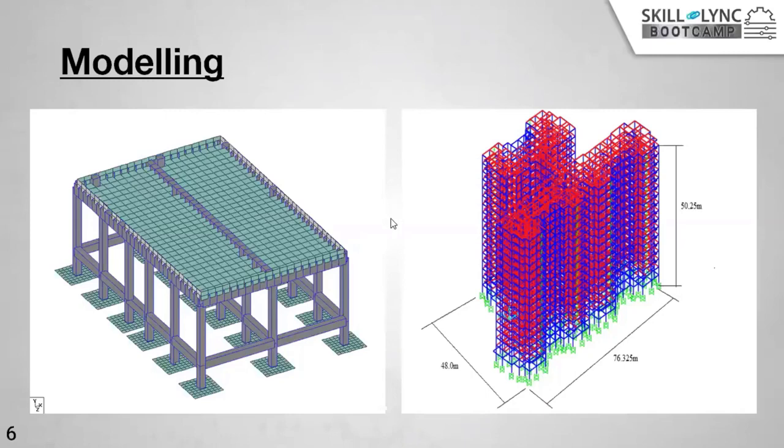So whatever software you use, the modeling is very important so that the load points are connected properly. The assumptions we made in the input must be perfectly transferred to the software. Otherwise, the software will analyze, but you will not get the proper result. Since the software is strong, we must have made something wrong in our input.